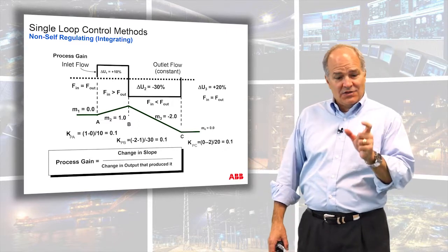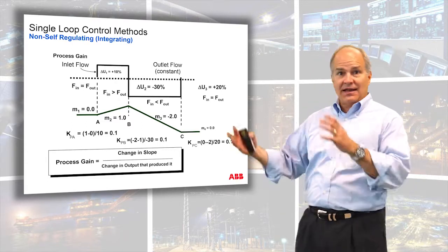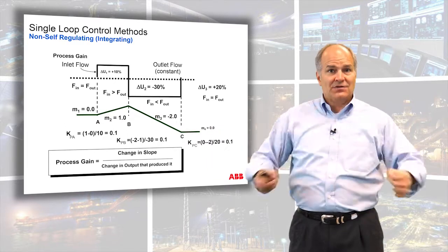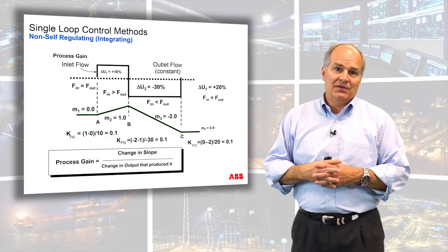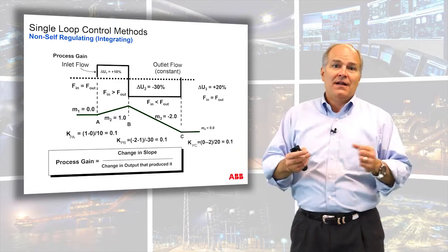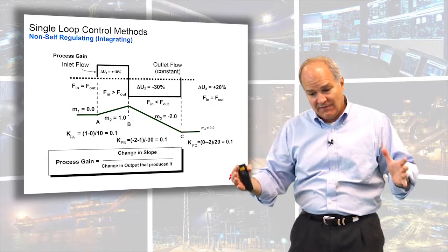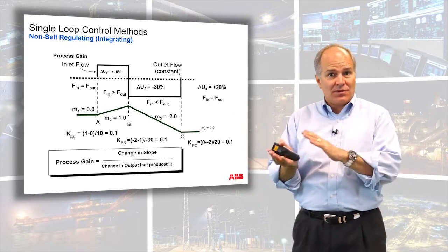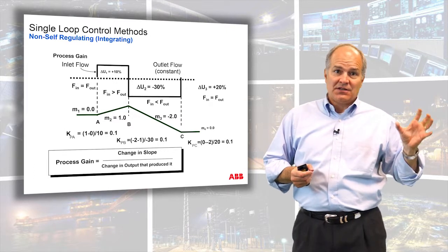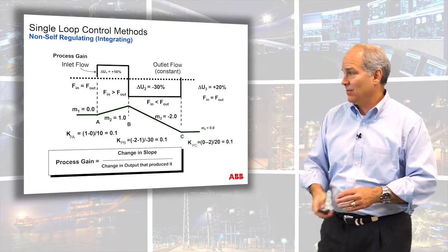It's one number that tells you how much power your actuation device has on that tank. If you have a tank that is as big as this room and this little bitty garden hose, imagine how long it takes for that thing to be filled. Or vice versa, I have this little bitty tank and I've got this great big fire engine hose. The size of the actuation device as compared to the volume or capacity of the tank is really what we're looking for. If I can know when I move this actuation device how much is coming out, that's what I need to identify, because that's what I use to calculate my tuning parameters.